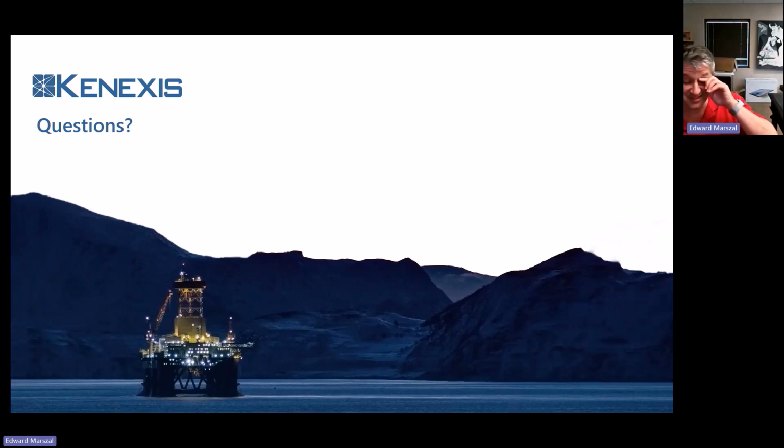Anything else, Chris? Well, there's one out there that says maybe off topic. I think the M out of N architecture formulas of 61508 are derived from an RBD or something similar. So it is correct to say that in industrial applications, if we can reconduct the system to an M out of N architecture of the 61508, the Markov modeling is always unnecessary.